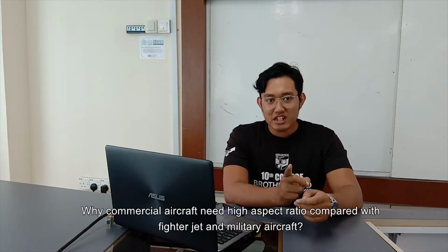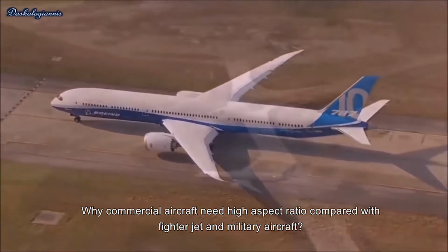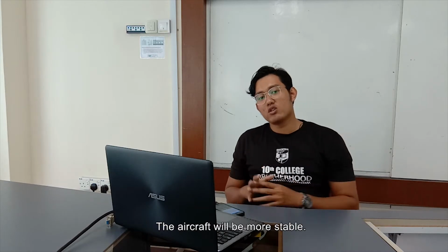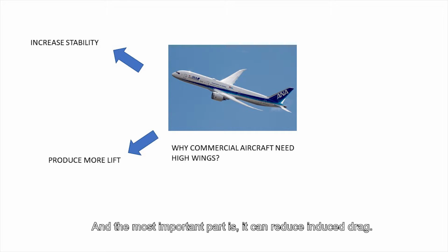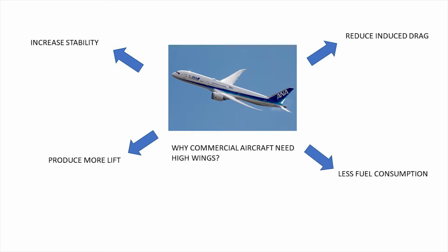Hello guys, now I will talk about high aspect ratio for commercial aircraft. Why do commercial aircraft need a high aspect ratio compared with fighter jets or military aircraft? It is because when you have a higher aspect ratio, the aircraft will be more stable. And when it has more stability, it also has more lift. And the most important part is that it can reduce induced drag. So the first enemy of the aircraft is drag. When you can reduce the drag of the aircraft, logically there is less fuel consumption.